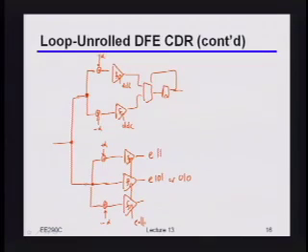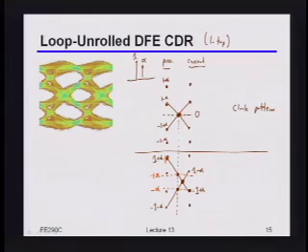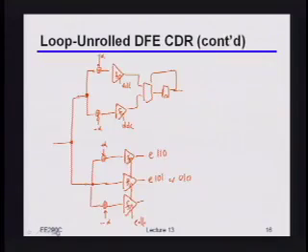Yeah, this would be a 110, right? Because if you look at the arc over here, the only way I can get to that top point is if both of the previous bit, the previous bit and the bit before it were both 1, right? And then I had a 0. Okay, so similarly, for that bottom guy there, what's the data pattern you're looking for? 001. Yeah, 001.